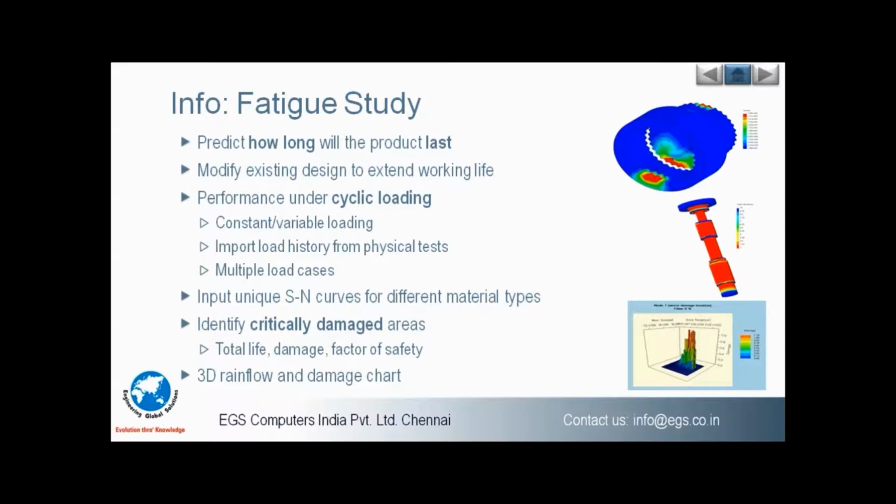And we can import all this history using the physical test of your products. And the material library is one such good thing inside SolidWorks Simulation, as the user can directly access the SN curves which are inbuilt inside the material database. So using this, we can calculate the total life of a product, damage, and the factor of safety.